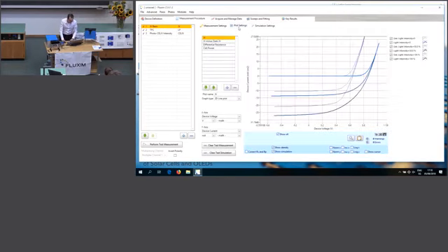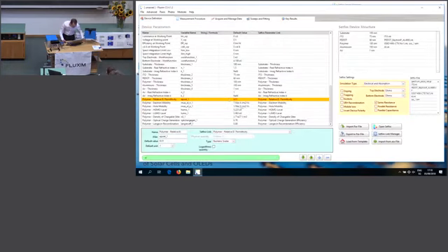We can go down here to plot settings, and we see now here the light, the solid, thin lines. This is the simulation, and this here is the measurement. So you see now in this case it doesn't really agree. So what we can do is we can say probably the charge generation needs to be a bit better. So we can go back and say optical charge generation, let's put this to 1.